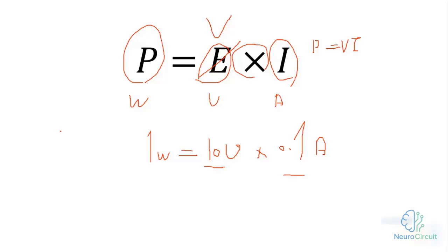This is because electronic components like resistors, transistors, capacitors, and integrated circuits (ICs) all have a maximum power rating, and if more power than this is applied to them, they will definitely burn out. That's why we need to consider the required power in our circuit design, calculations, and the components we use, and take all these factors into account together so that our circuit works properly.